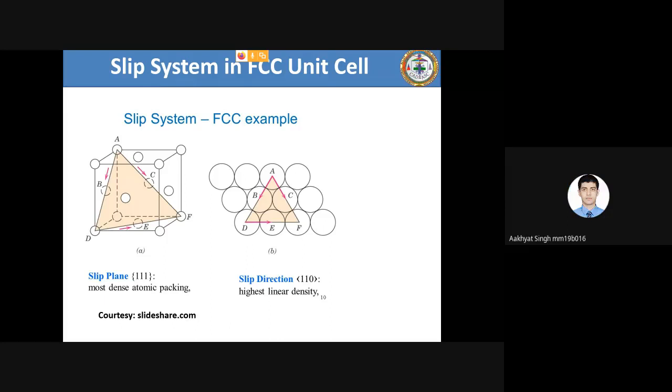So this is like parallel planes. That's the reason for our calculation. How many slip systems are there? We take 4. But in total, you are right, it is 8. But partly Aditi is also correct, because that is bar one, bar one, bar one, and 111. So they are parallel, so we cannot consider both, right?